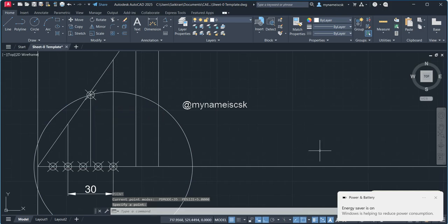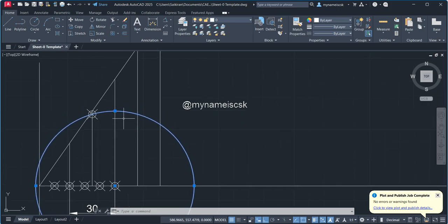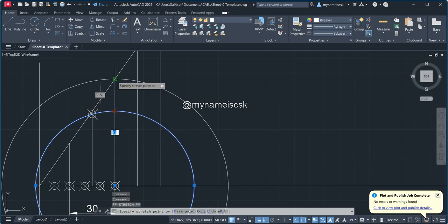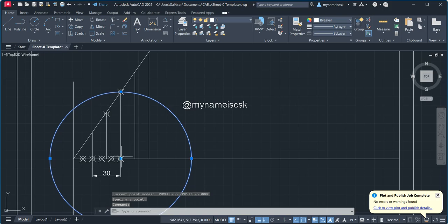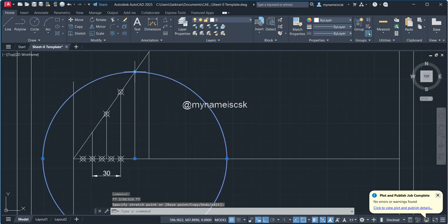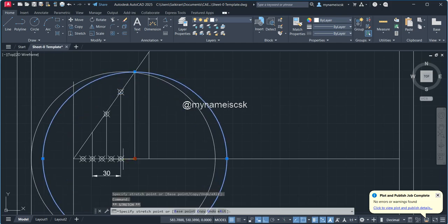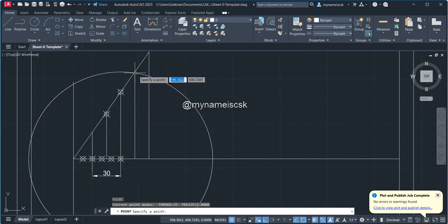point. PO, enter and point. Then again I'll move my circle to second. So automatically I'm here only in the directly I'm moving here, and again PO, enter and I'll place the point. I'll select here. Again I'll move to 3 and 3 dash. So this is my 3 and this is my 3 dash is the radius. Again I'll move to my focus. Then PO, enter and done.